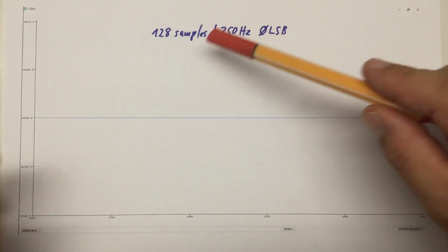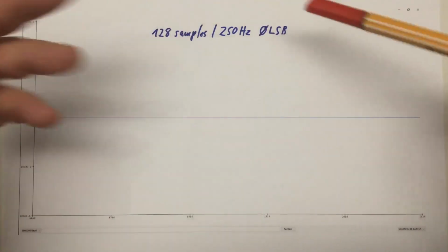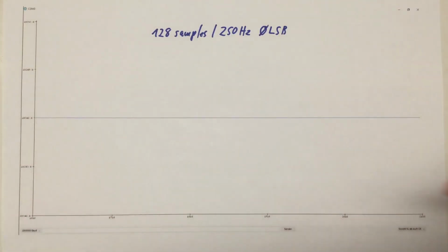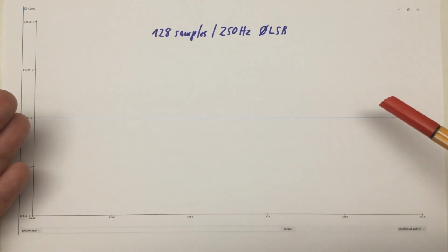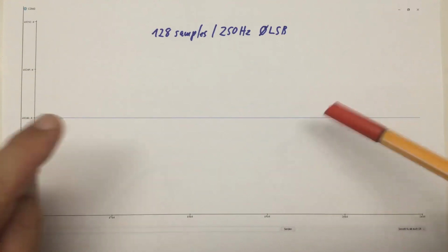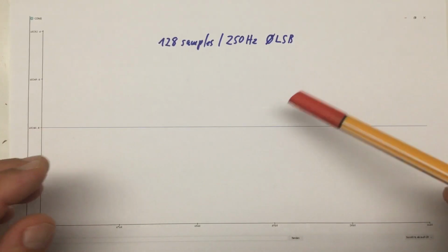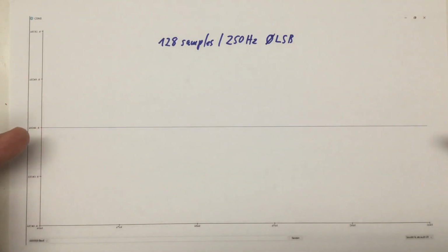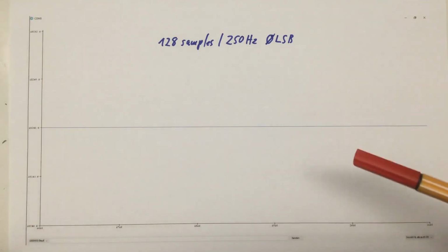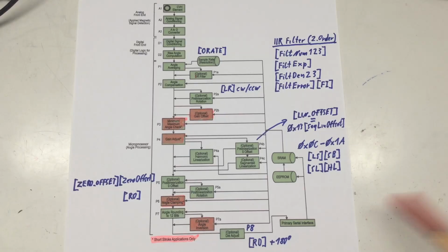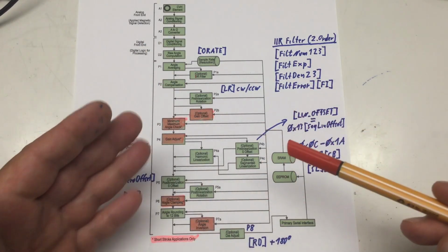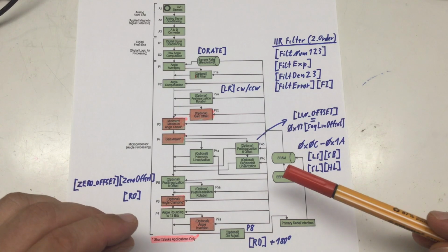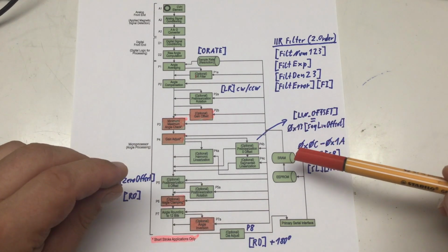And finally, at 128 samples averaging and output rate, of course, down to a meager 250 hertz, we had a flat line. No noise observable at all. And that's, for a change, a magnetic sensor I really like. That's how the output signal has to look like, at least in my book. So that was angle averaging via setting the O-rate parameter on the extended address.